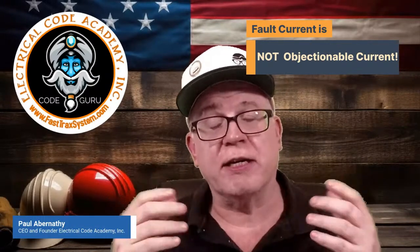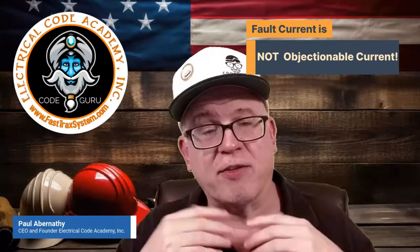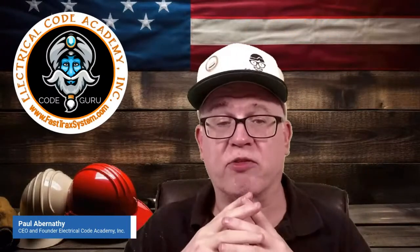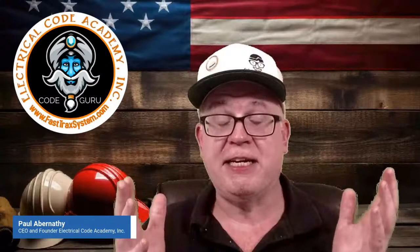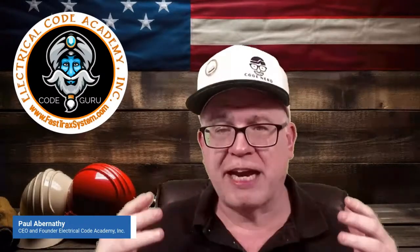It's for fault current, but in clearing an overcurrent device, that's the primary function, although it does tie metal parts together and serve a bonding role as well. We find all that in 250.4 of the National Electrical Code. Reading all that, it's a great read. But when we do that improper case to neutral connection, we create a hazard.